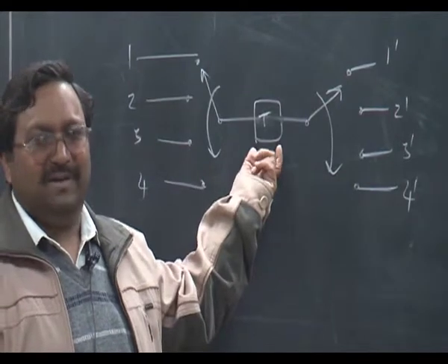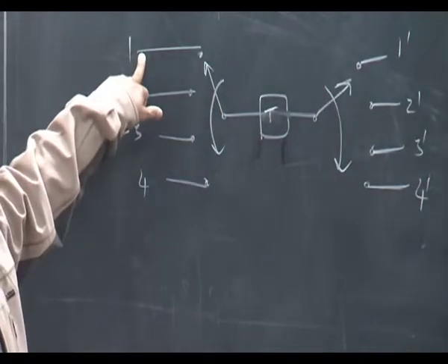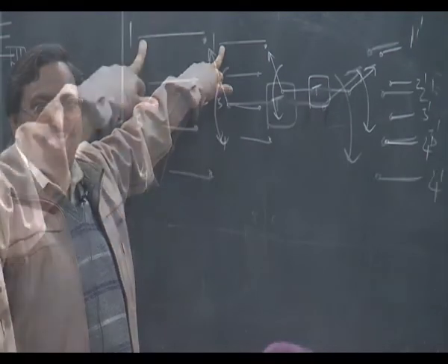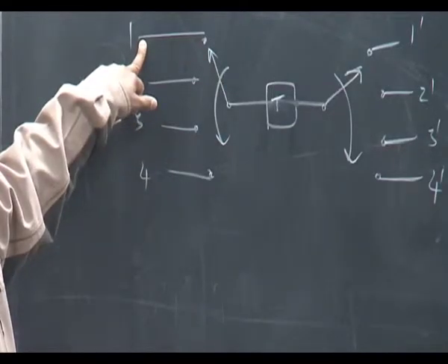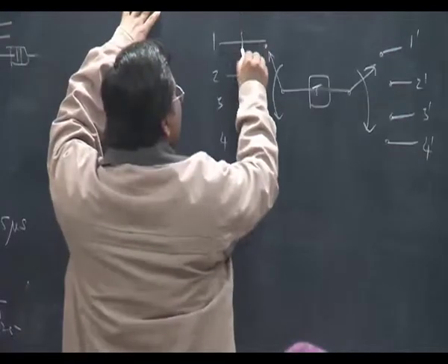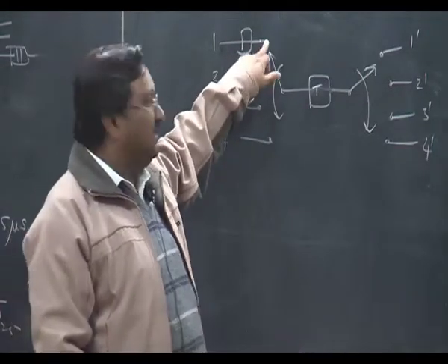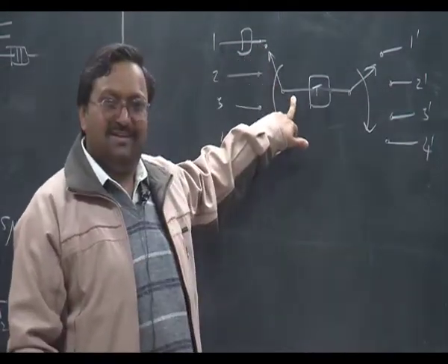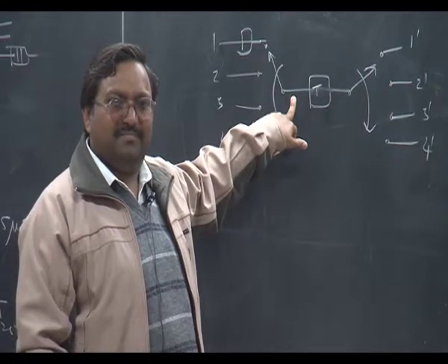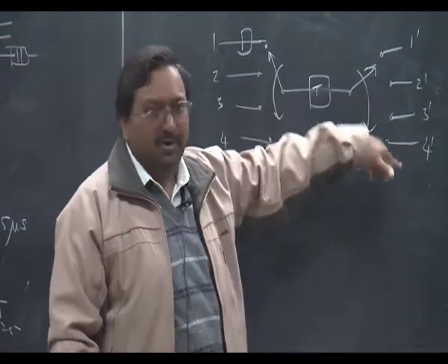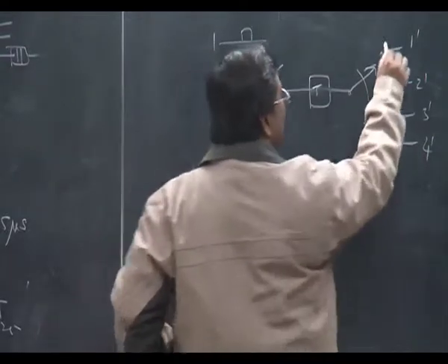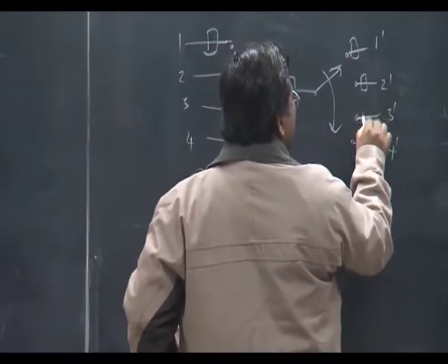So I am not worried about this input being sampled only every 125 microseconds. If it were analog, there is an ADC and then one sample generated every 125 microseconds that always goes into the first slot of the frame, and that can be switched to any outgoing port, and there is a DAC you will put, and it will become nothing but a crossbar.